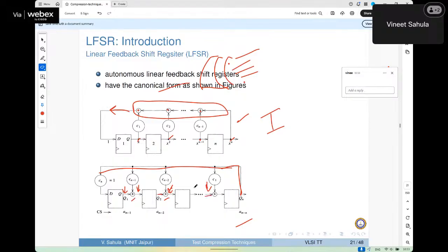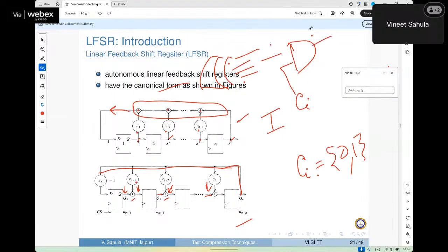the present one. Right? The C1, C2 are multipliers, but C1, C2 are all modulo 2 numbers. So it is a kind of a switch. Ci connects input to output or doesn't connect, depending on whether it's a 0 or 1. That's all. So these C1, C2, Cn are nothing but switches. If they are connections, Ci being 0 means no connection, and Ci being 1 means a connection. That's all, nothing else. In a generic form, we analyze this in detail, quickly, in 10 minutes, and then see the signature analysis.